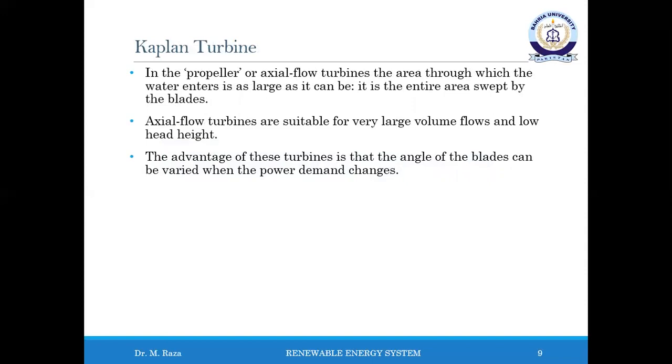Double regulation of turbines is a feature now widely used for river installations with significant flow variation during an average year. In a Kaplan turbine, the optimum blade speed is greater than the water speed, as much as twice as fast. This allows a rapid rate of rotation even with relatively low water speed.